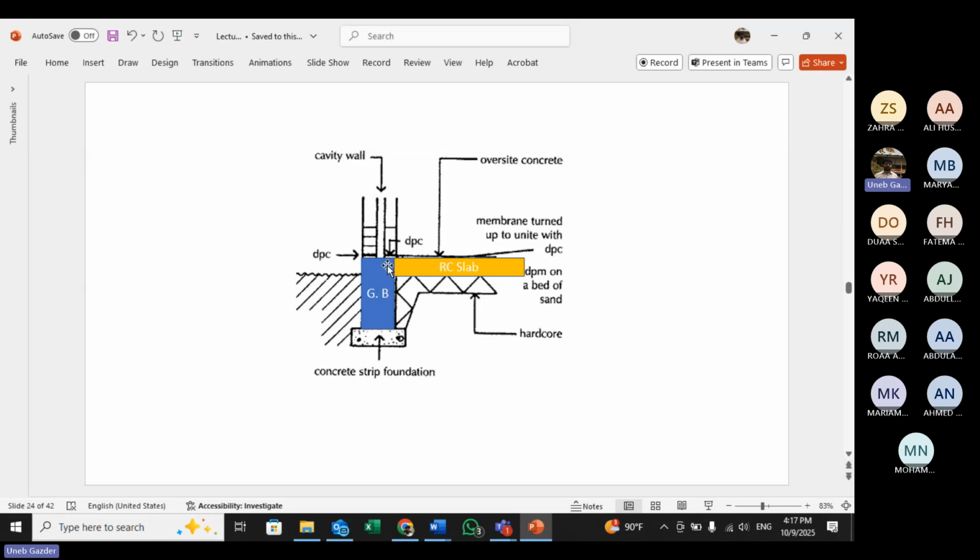Now you can see here they are using the wall which we typically use in Bahrain. We don't use this type of construction in Pakistan, by the way. I'm talking about the walls, so this is very much relevant to you guys. We have the external wall and the internal wall, external here outside on your left-hand side, internal on the right-hand side. Between them, we have the cavity. Cavity means a spacing between the two faces of the wall.